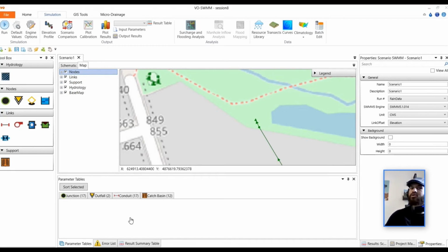What I actually want to do now is add my DEM file to the model, because the DEM has the physical characteristics of my watershed, of my region, of my area. So I need to add my DEM. And after adding the DEM, I also have the shapefile of the buildings of that region, of that area. Using those two, I can generate the flow path and the sag area. I can find out where my sag area is.